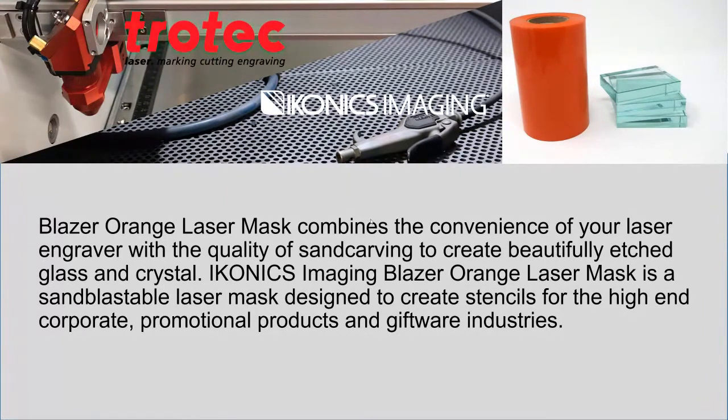What that means is it doesn't have any toxins or any other materials in it that can't be laser processed, such as PVC vinyl, which some people will use vinyl cutters for. So the sandblasting mask specifically designed for lasers is what's necessary in order to make this process work.